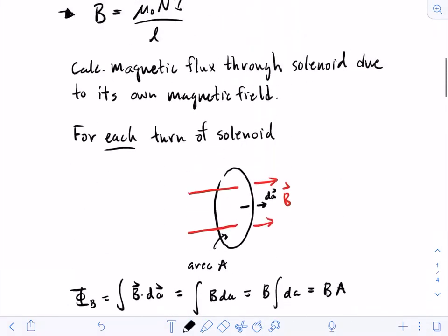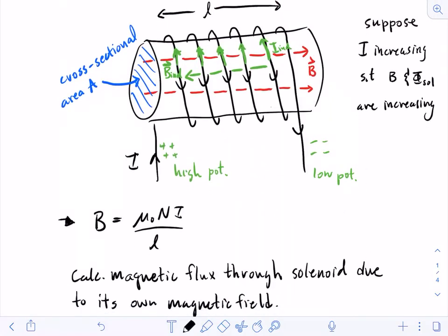And so if we write this as delta VL, so let's write this as V1, V2, so that delta VL is V2 minus V1. So we're going to go across this inductor in the direction of the original current I. Then the final potential is a low potential, and then we're subtracting off a high potential. And so it must be that delta VL, in our case, is a negative number.